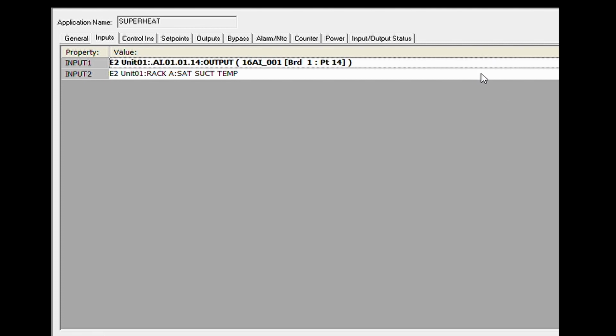So please don't set up alarms on individual inputs. If you're going to do an alarm, do it on, see how it's got this little alarm bell right there? I set that up to be an alarm now. So if you see a little alarm bell next to an input or an output, that is an alarm for that input or output. Like I said, it's better just to do the alarms in the alarm section unless you absolutely have to set up an alarm that way.